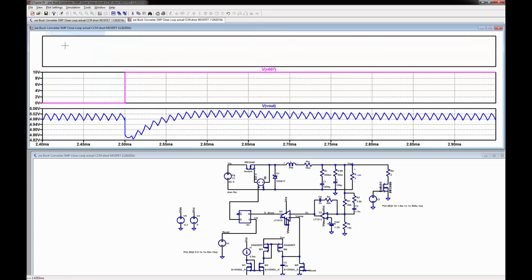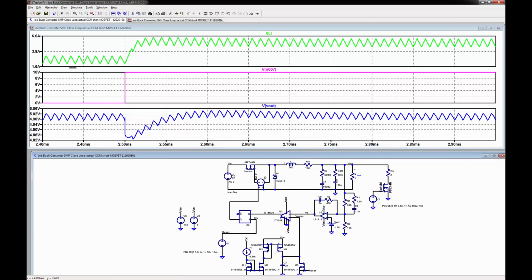Let's open that up, and we look at the current in this inductor. And lo and behold, just like I said, this is at 2.5 amps, and all of a sudden it's got to get up. Well, it doesn't get up right away. It takes a couple of cycles to go. This delay is being supplied by this cap, so it's sucking energy from that cap. To make this tighter, we can increase the cap and lower the ESR, and we'd have less of an overshoot here, undershoot. The same way is an overshoot.